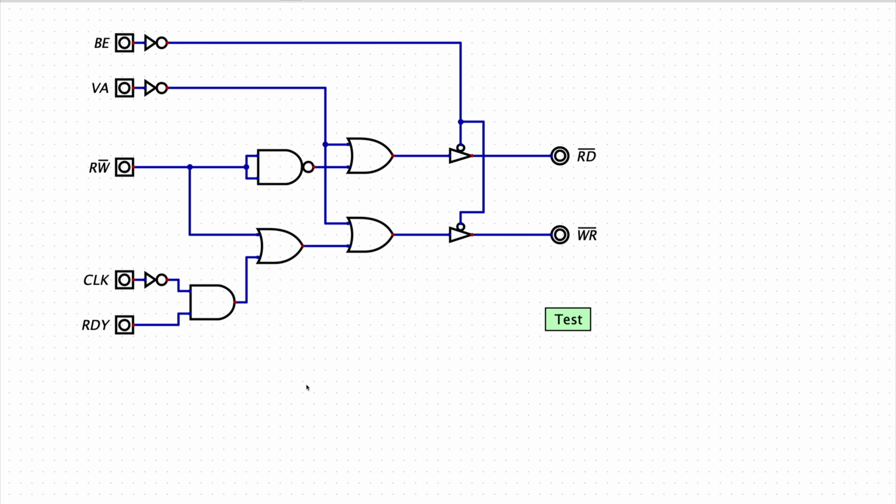There we go. And finally, the last change I want to make is regarding the read signal. At the moment, we are reading during the whole clock cycle. Some devices actually use the first part of the clock cycle to do DMA access. For example, the Apple II uses this scheme. It does video access when the clock is low, and the CPU can access memory when the clock is high.